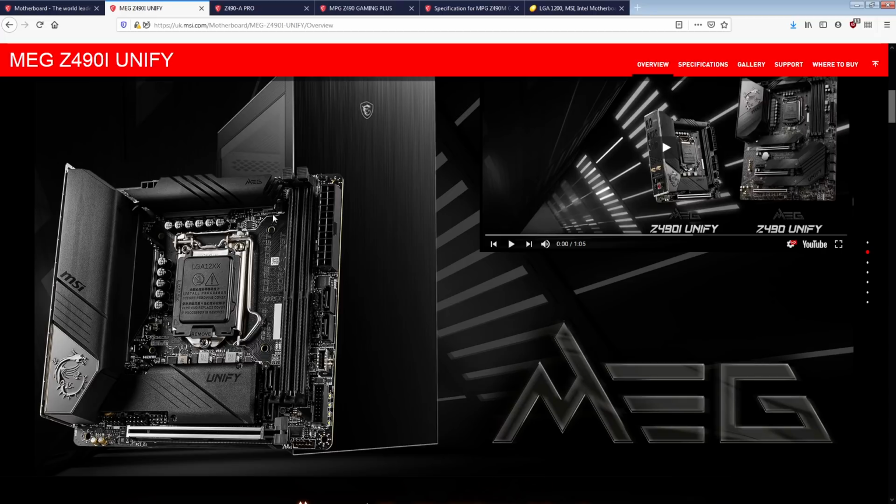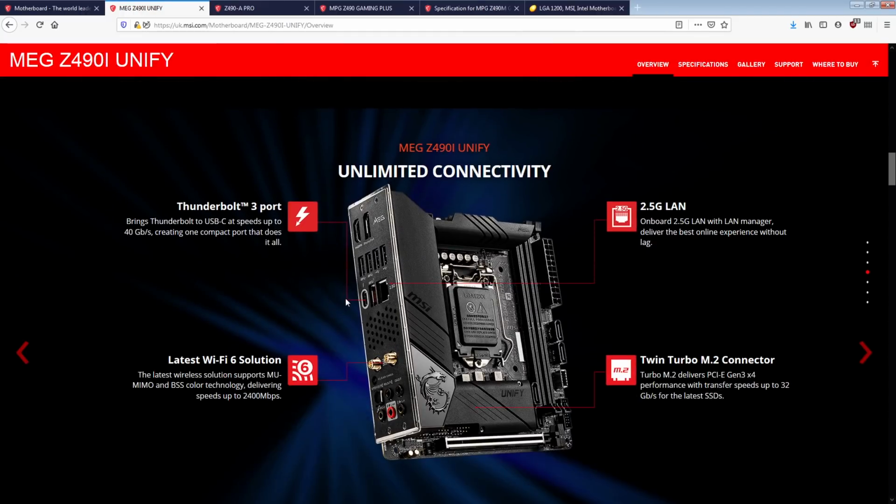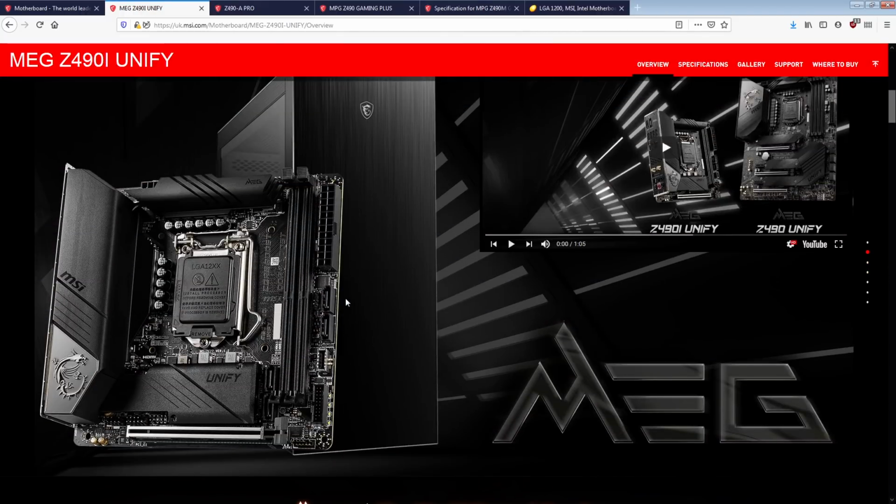As far as the through holes, I'm just not a fan. To be fair, the second best Z390 motherboard I tested was a Maximus 11 Gene in terms of transient response, and it uses a bunch of through hole capacitors, so they can work. The thing is, this doesn't even have that many of them, which is another concern. One of the workarounds for using a higher ESR, higher ESL capacitor is to just put more of them in parallel, but you can't do that on an ITX board because there's not enough space. There's like 8 caps total here.